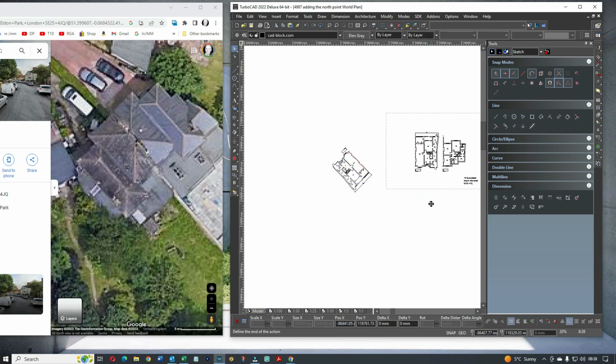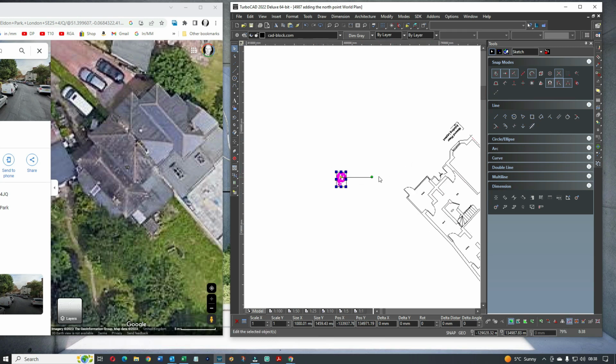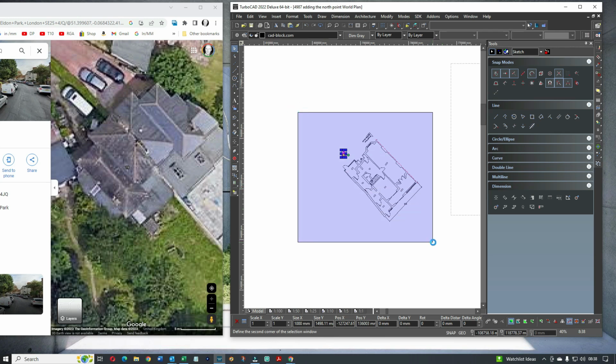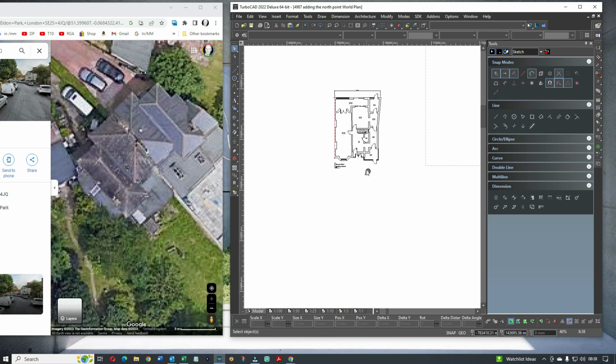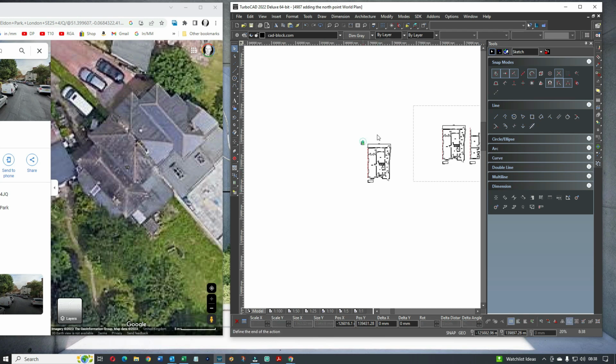So now we get the north point, and we also make that tip north. Now, as you can see, this drawing and the house are absolutely accurate. So what we do after that is we turn the layout plan with the north point so that the north point is actually showing correctly. You get that? That north point is now showing correctly for that property.